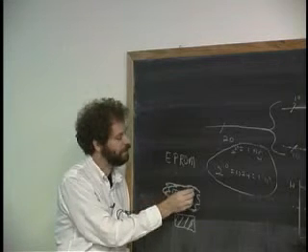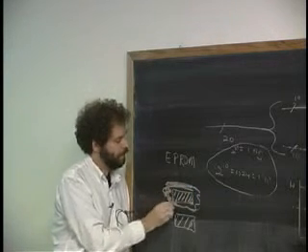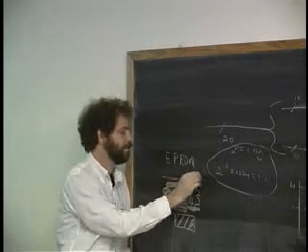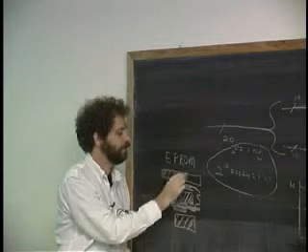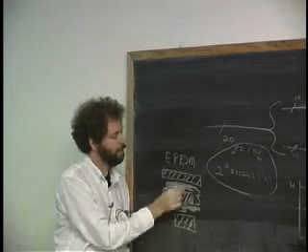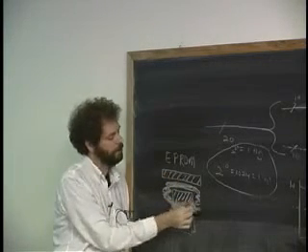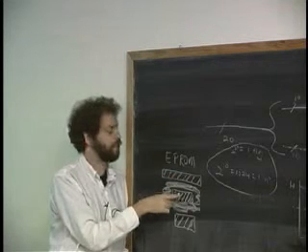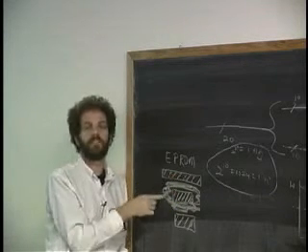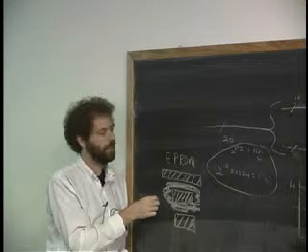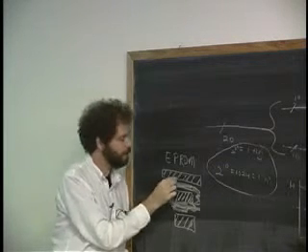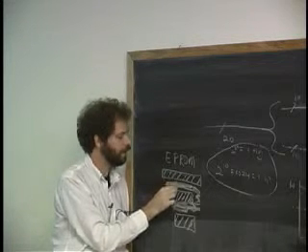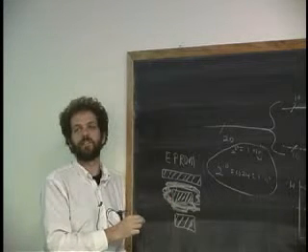Well, it turns out the glass is an amazing thing. It has a characteristic of two things. First of all, you put another plate on here of semiconductor. So this is really 3 plates, like so. And even though there's glass here, if you put enough voltage on this guy, like 20 volts, most of these things run at 5 volts, but if you put 20 volts, due to a process in physics called tunneling, some of the electrons here are so hot to get to the other side that they will squirm their way through the insulator and get to it anyway.